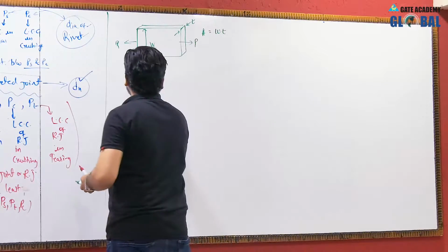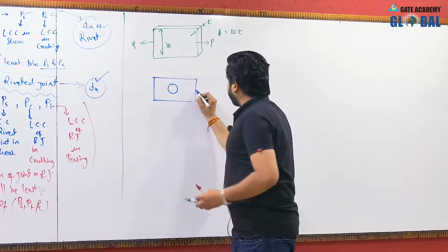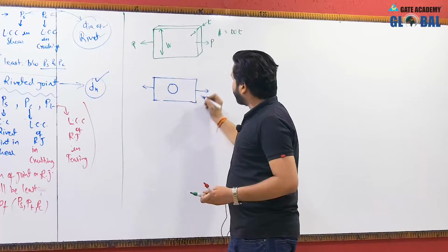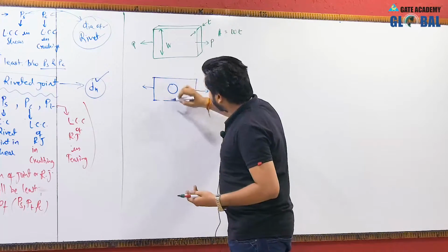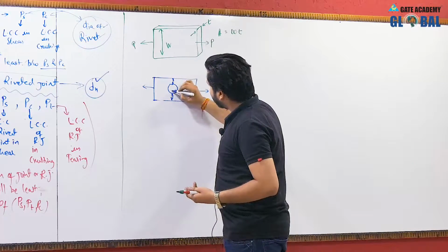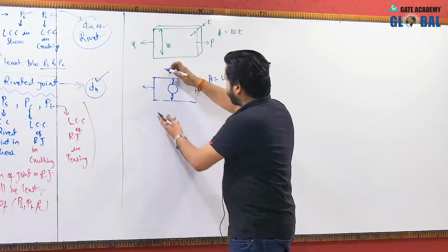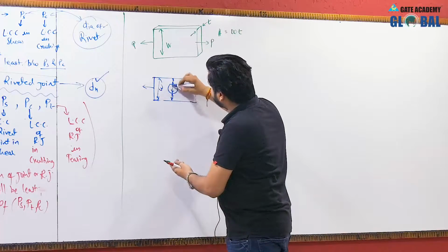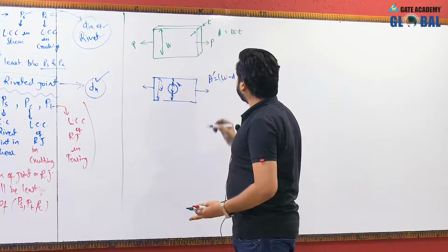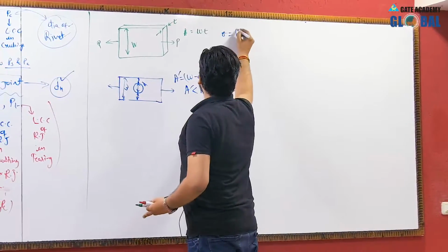Now if it has a hole, then the stress induced in the component, or you can say in the plate, will increase, as here we have removed some material in order to form the hole. So the total area available will be A equal to W, this is the width of the plate, W minus D into T, okay. And this area, let us say this is A dash, so A dash is less than A, okay, and stress is equal to P by A.